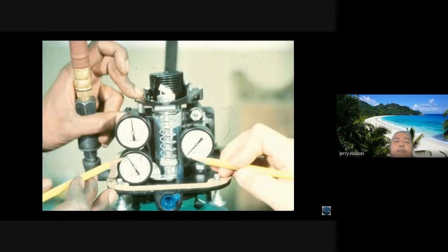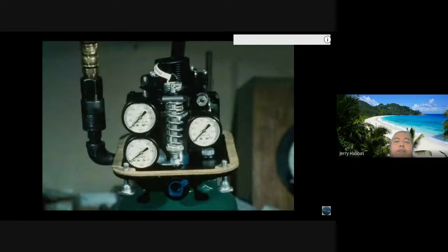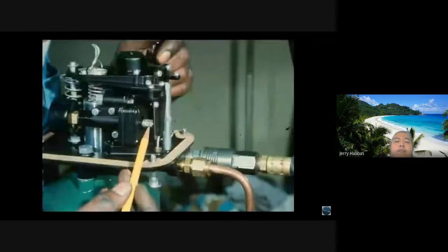Now, suppose we increase the instrument signal pressure, but the top cylinder pressure remains at 0. We can definitely conclude that the actuator is in bad order. We have isolated the problem to the actuator, and we can further isolate the problem to the positioner, since it supplies the cylinder pressures. Furthermore, we can isolate the problem to this relay, since it is the one that loads the top cylinder. Notice that the flapper is covering the nozzle. This definitely indicates that the relay is at fault.